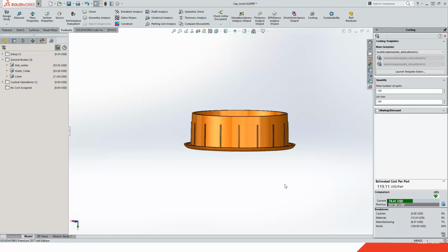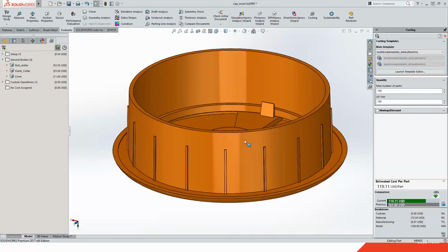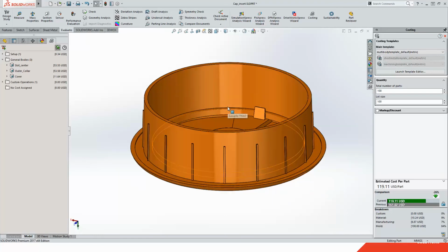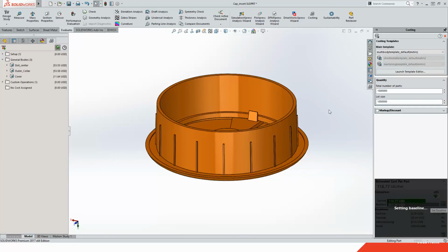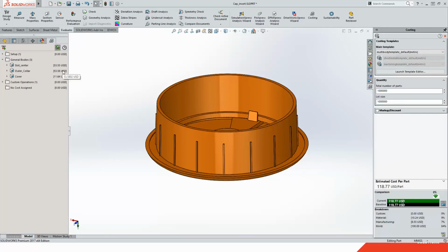We'll go back into our total cost analysis, and if we decide to 3D print one part and plastic injection mold the rest, we're looking at an assembly that dropped about $35 on this. Now, this is one of those things where with plastic injection molding, the number of parts is definitely going to affect the cost of any one of these things. So if we want to take what we're currently at as a baseline, I want to show you that these $53 parts is because we were only making 100 of those on one particular mold.